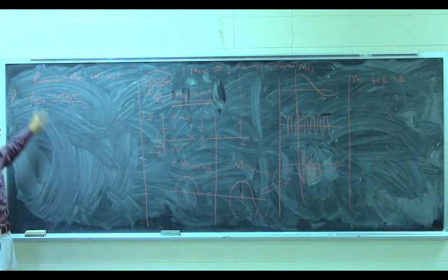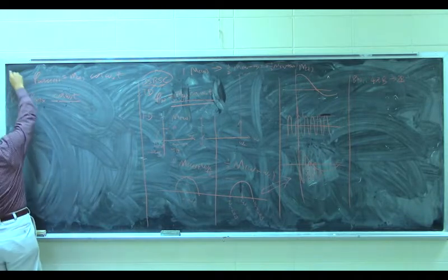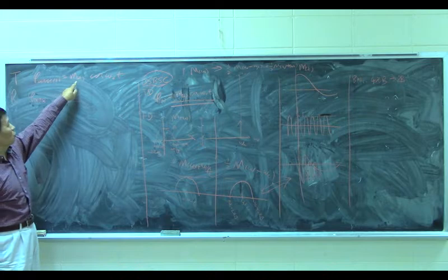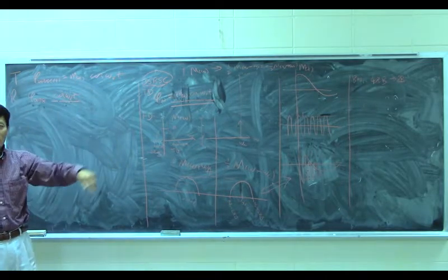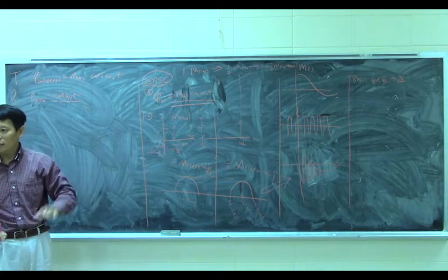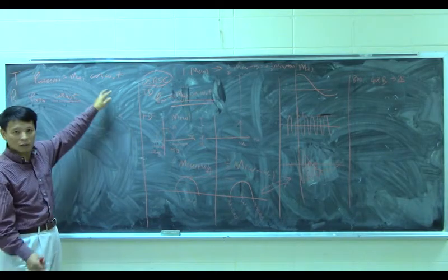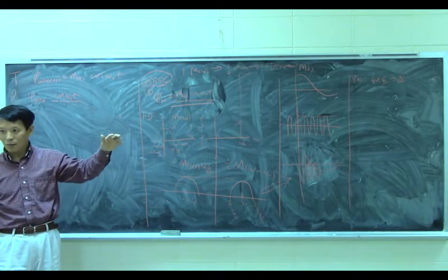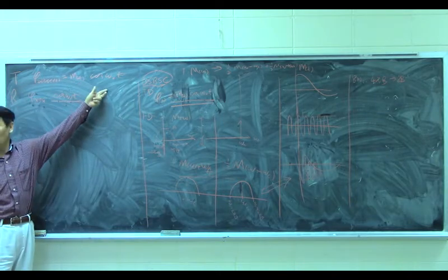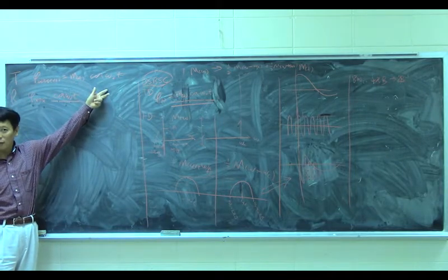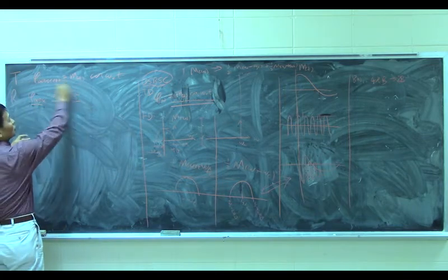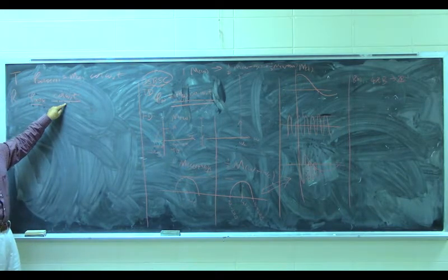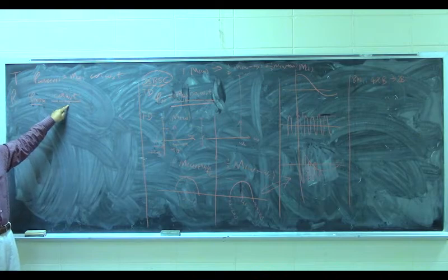At the transmitter, you multiply the baseband signal with your carrier and transmit it with the cable or wirelessly, no matter what. Your work is done. At the receiver, you receive this one. What we need to do is multiply it with the carrier signal again.